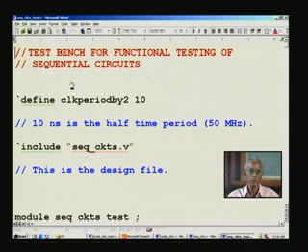Mind you, all the hash delays that we have spoken about will be filtered out during the synthesis process, because Verilog design using RTL coding guidelines is fundamentally meant to get rid of the technology dependence, right. We should be independent of the technology, and that is possible only if there is no time element, but we have introduced time element just to facilitate simulation, and therefore it appears only in the test bench, right.